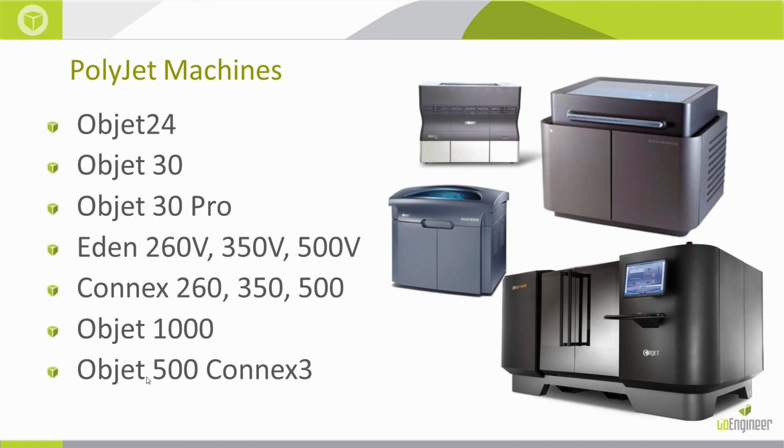The Eden level, the 260, the 350, and the 500, those are the machines pictured in the middle left there. These machines open up the door to the rubber-like material, and they come in 3 sizes. The only difference between the 260, 350, and the 500 are the build sizes. Those numbers, 260, 350, and 500, are the distance on the x-axis of the build envelope size.